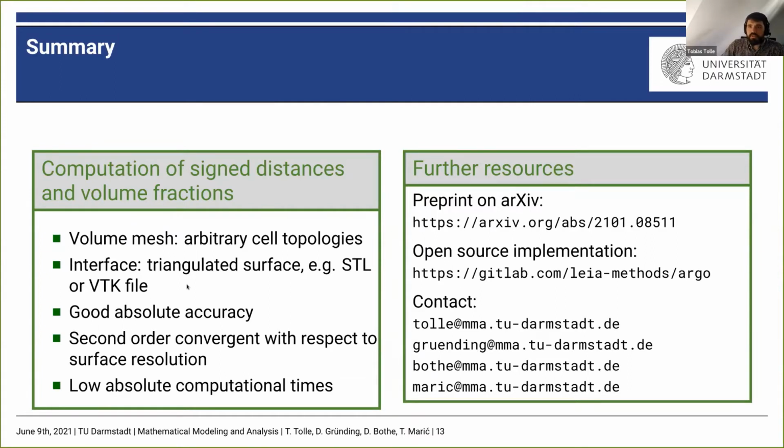We achieve good absolute accuracy, and we also have second order convergence with respect to the surface resolution, which was to be expected since we use a piecewise linear approximation, and which is also nice. The computational times are low. The cases shown here have all been computed in serial, and none of them has taken, I think, more than 2 minutes to initialize.